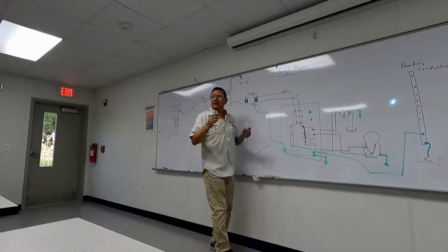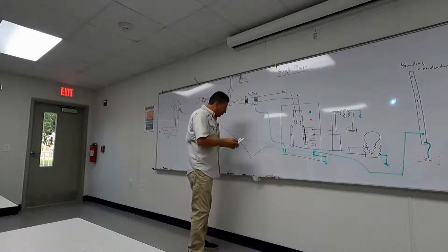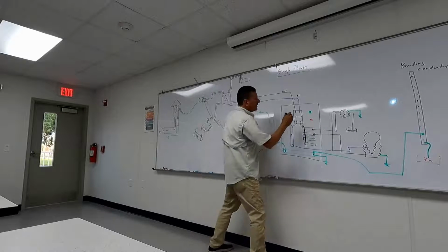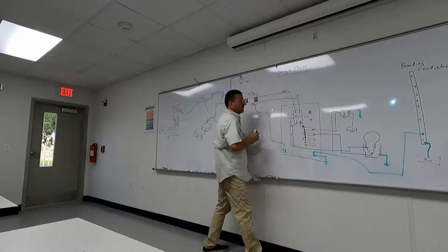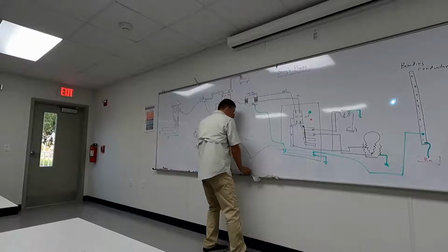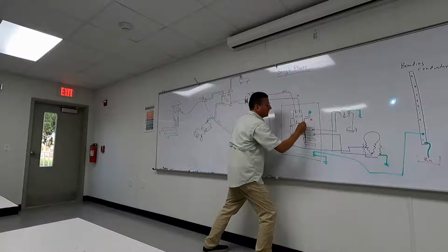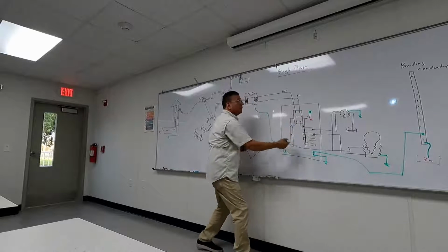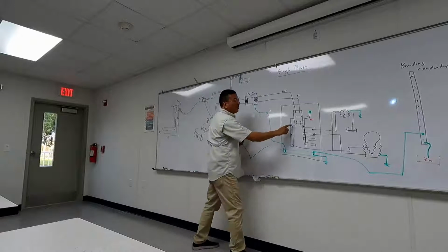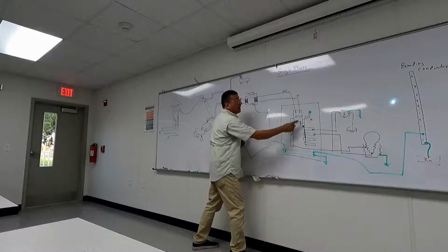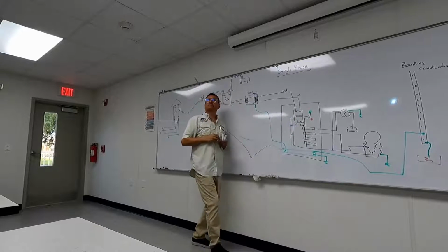Basically this is an LED with two terminals. One terminal should be connected to the neutral bus bar, and the other one to the hot bus bar. If you have power in the hot bus bar and in the neutral, the light should be on.